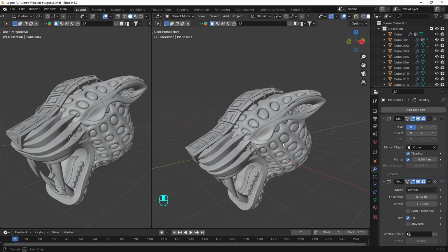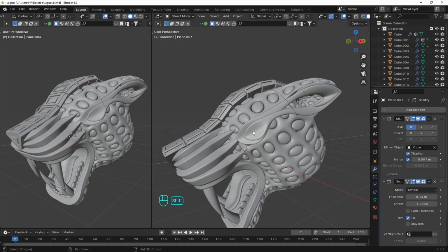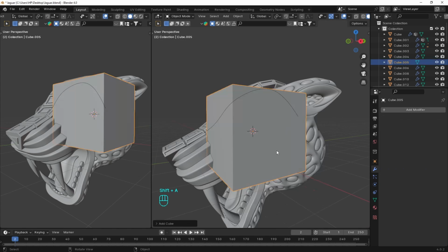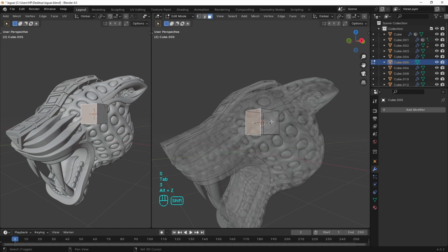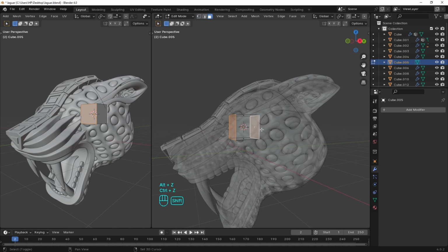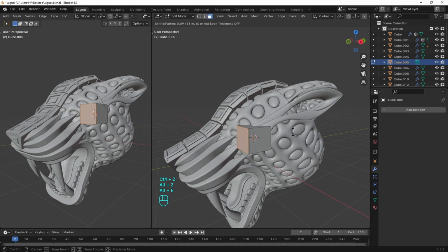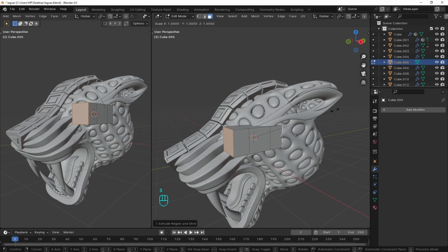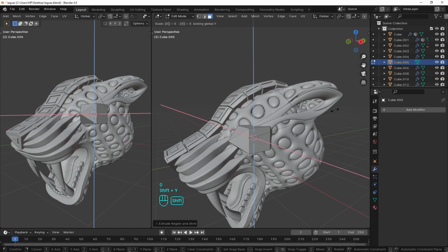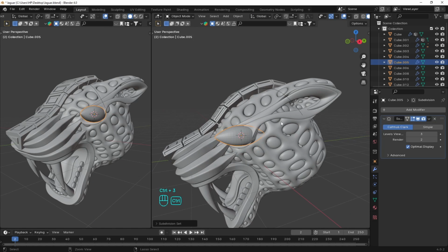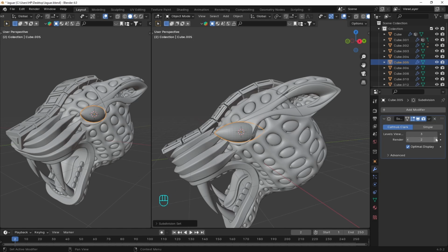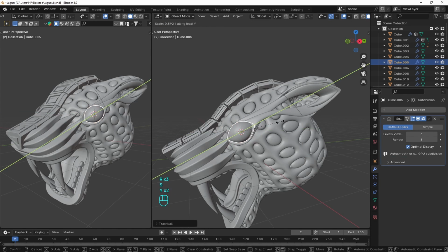Do something like this, and we can place the cursor there with shift and right click. This is useful if you want to add the object on specific places, for example. For the eyes we can extrude, then scale down these faces to 0, excluding the Y axis by holding shift. Subdivision and edit the size along the local axis.